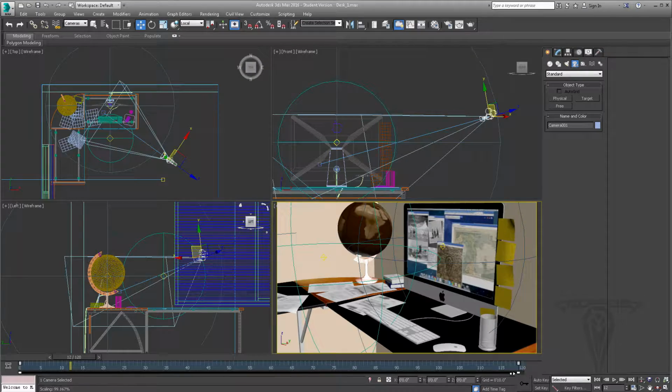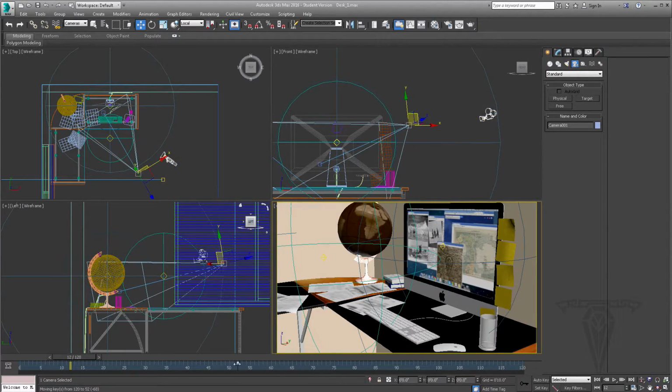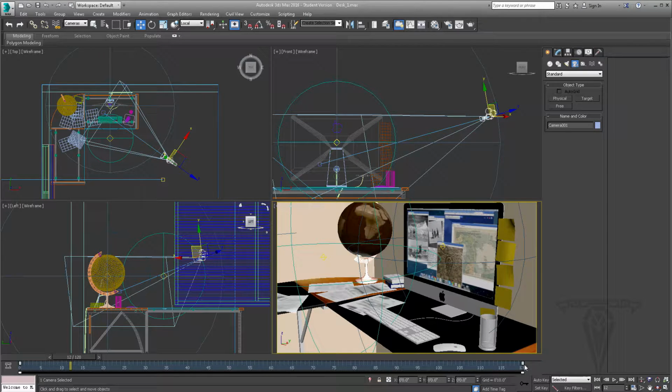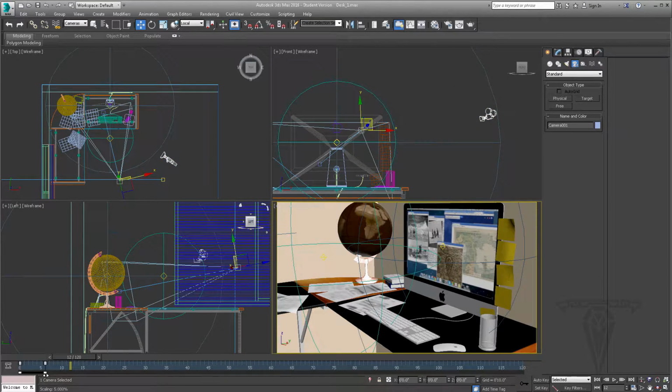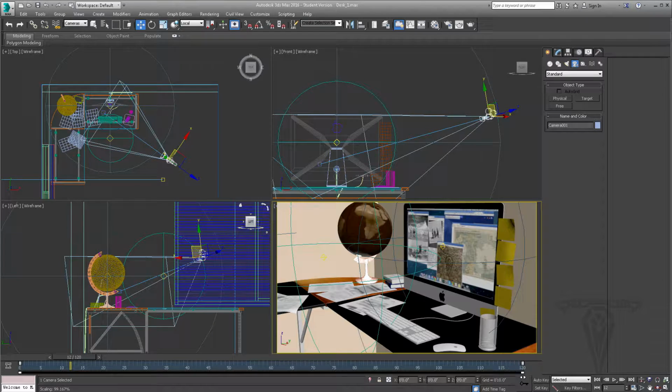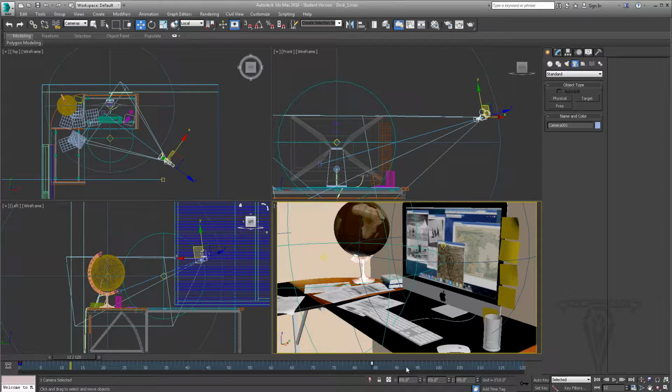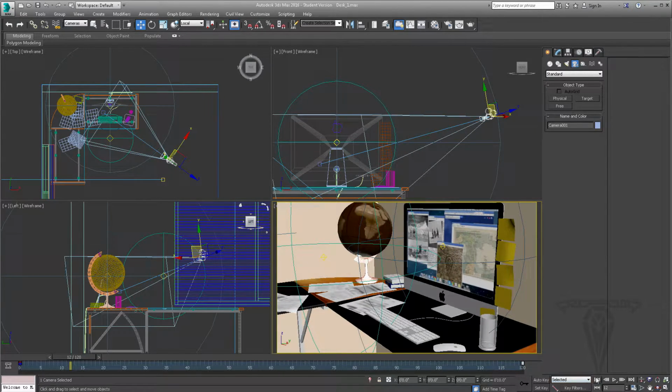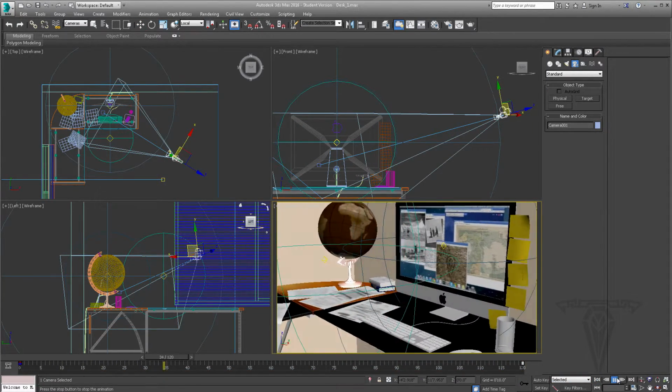this bar down here gives me the ability to slide the keyframes, or I can just grab the keyframe and slide it. But the problem is when I grab the keyframe when they're both selected, it slides both of them. When I grab this bar down here, it actually pinches the keyframes together. Okay? So that's how you control the timeline. Or you can just grab an individual keyframe and move it. All right, so there is our animation.